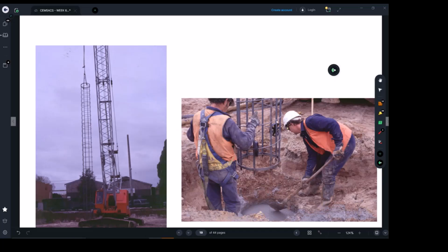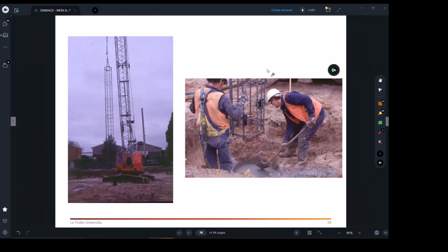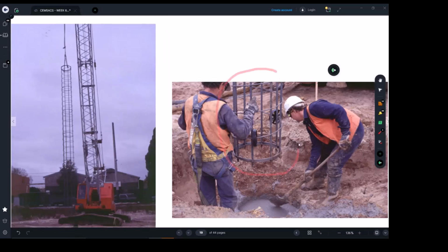First, you can say the concrete needs to be mixed with super plasticizers. We said that in our notes for you. The reinforcement components, in terms of stirrups and bars, need to be welded together. So these are the considerations you would need to consider.